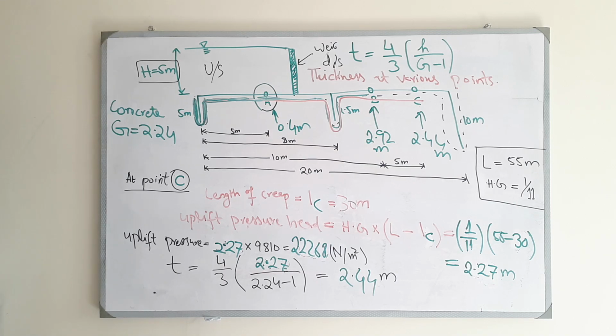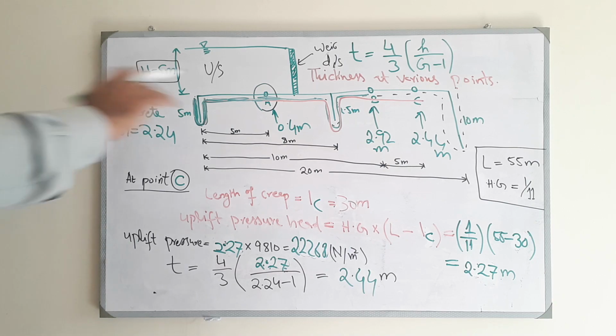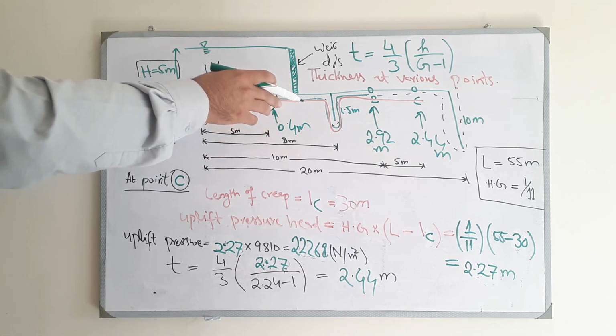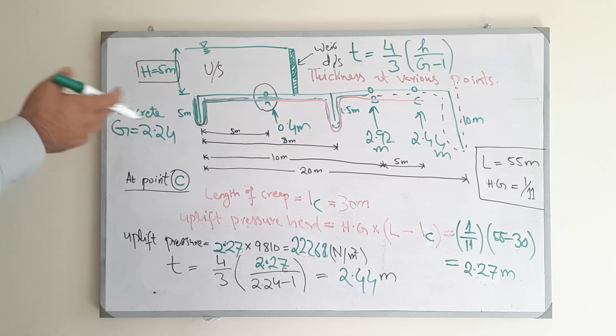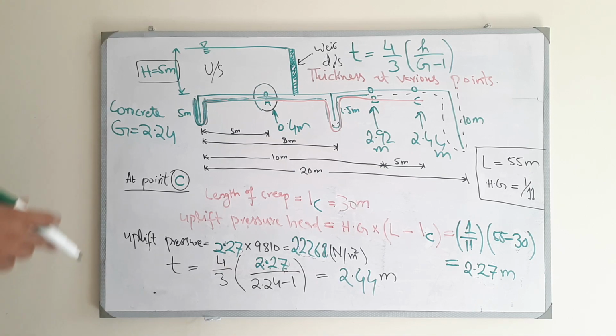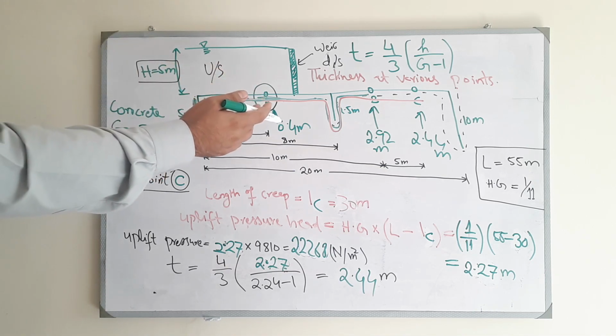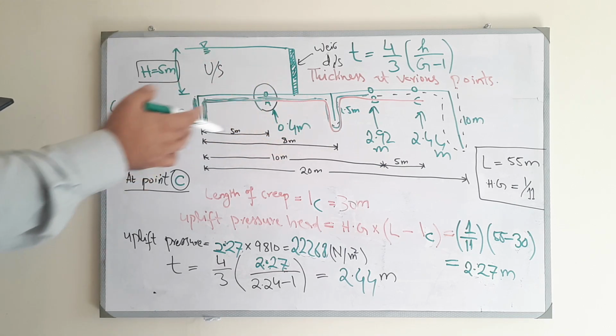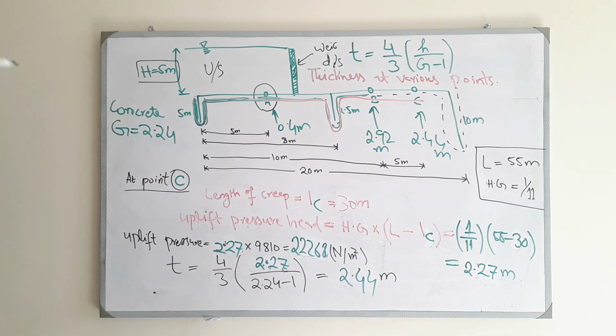Later on, Lane made the distinction between the horizontal creep and the vertical creep. So this was basically one of the limitations, and he didn't explain the idea of exit gradient, that safety against undermining cannot simply be obtained by considering a flat average gradient, but by keeping the gradient well below critical. So he said that the gradient is like flat and constant.